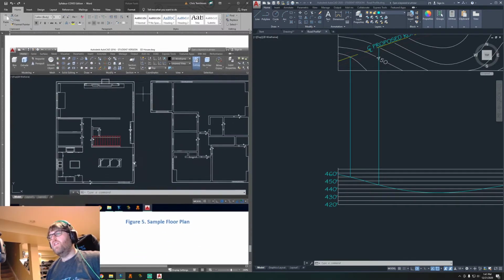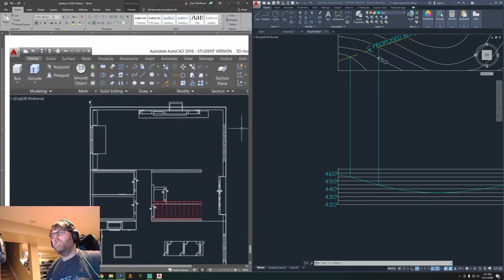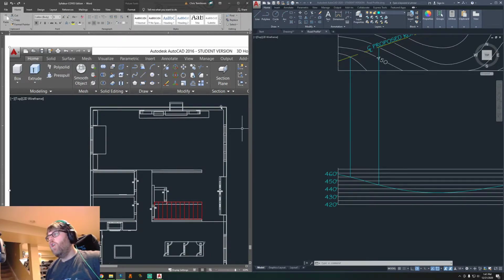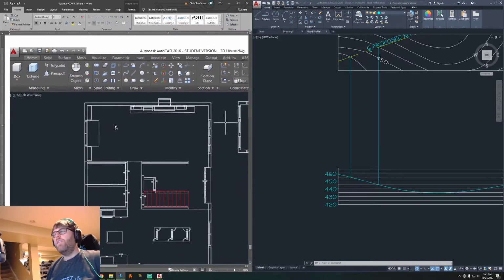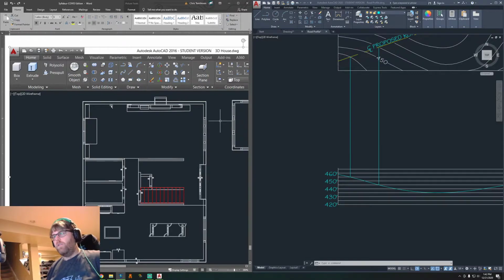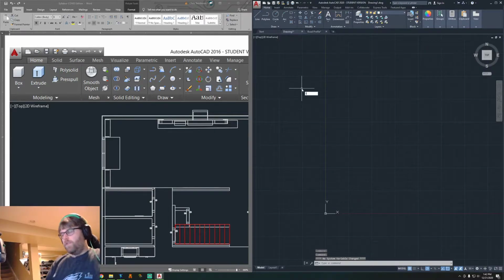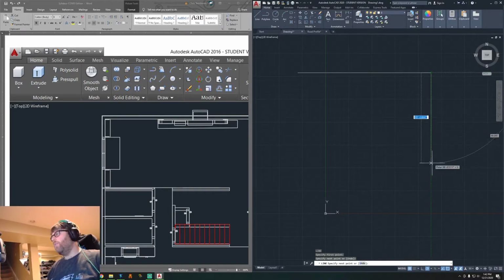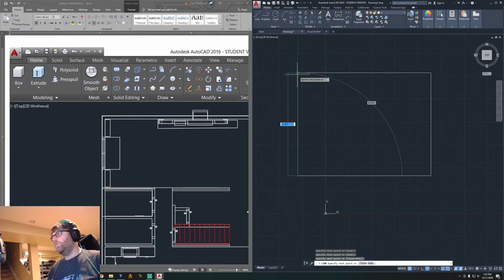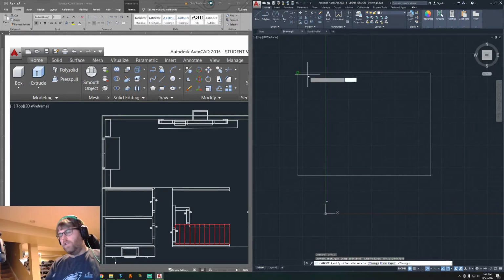But you'll see that the walls have thickness, so you have an outer edge and an inner edge. You could use something like 4 inches, 6 inches, however much. You could look at the walls in your house, maybe somewhere around 6 inches. You'll create your rooms and you'll offset these lines. Say our house is some type of box. You offset it 6 inches in.